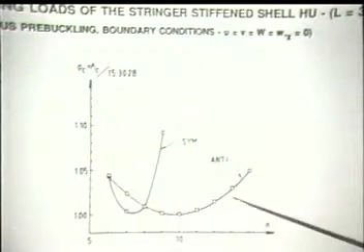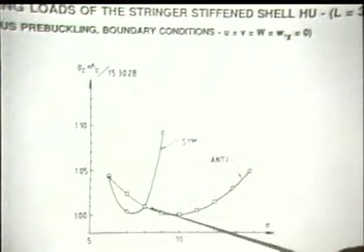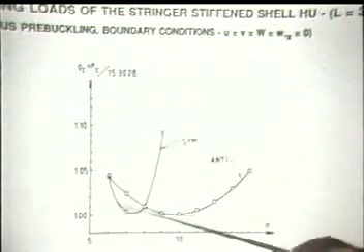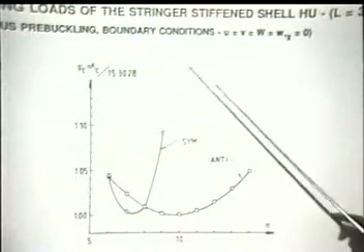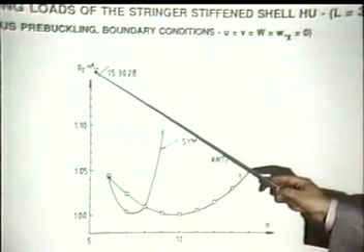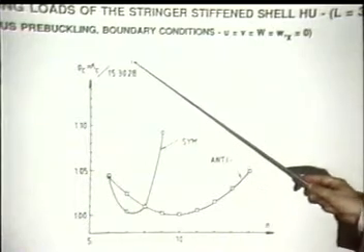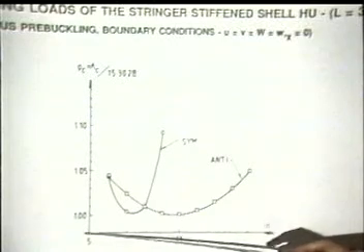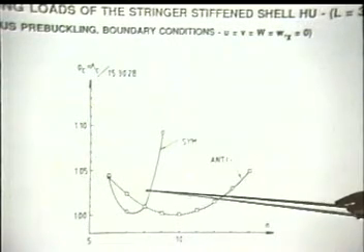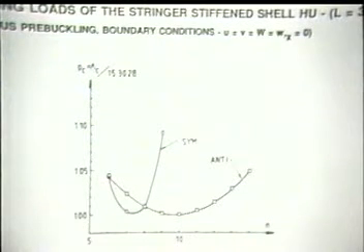You will see it. For instance, here, to this scale, there are two of them. One is symmetric in the axial direction, and one is anti-symmetric in the axial direction. I always like to work with rho, which is a kind of normalized eigenvalue. What I do is take the eigenvalue and divide it by the lowest value, which here is 15.3028. This here is the number of waves in the circumferential direction, and I will look at n equal to 8. There exists a symmetric and there exists an anti-symmetric very close to each other.